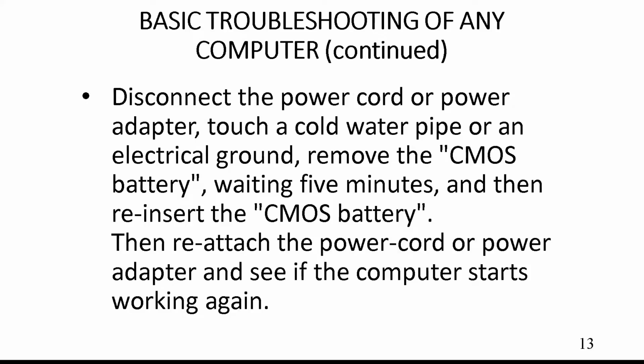Finally, if nothing else works, you're free to locate the CMOS battery and yank it out, wait 5 minutes, and then reinsert it. Now, you cannot have anything powered up when you remove the CMOS battery, because it'll cause problems and may even blow your motherboard. And you can't have any kind of powered up USB device, such as an active USB cable or a hub powered up attached to your computer. Any kind of DC power going into your motherboard will cause massive problems when you pull out the CMOS battery.